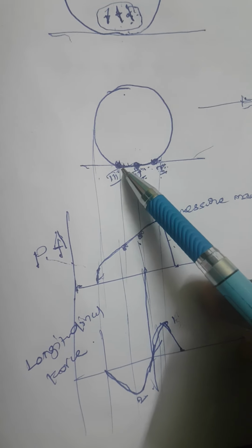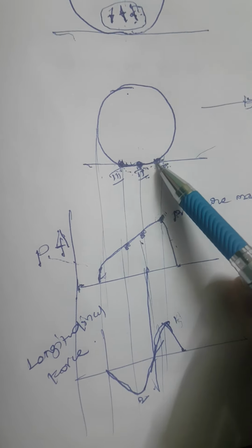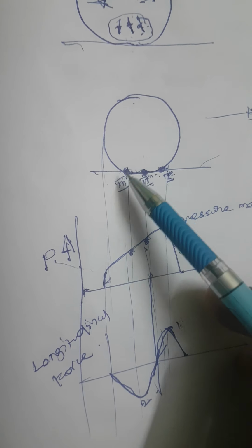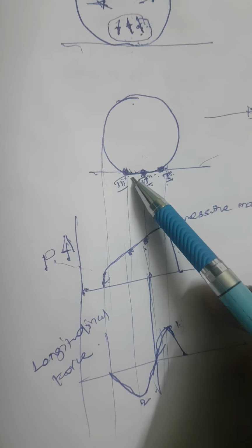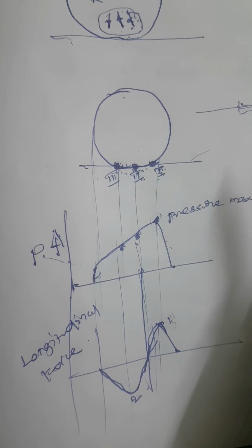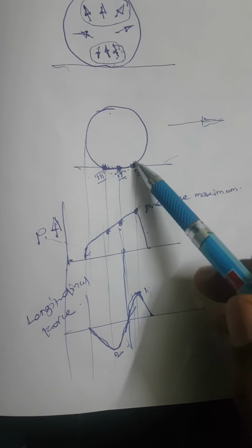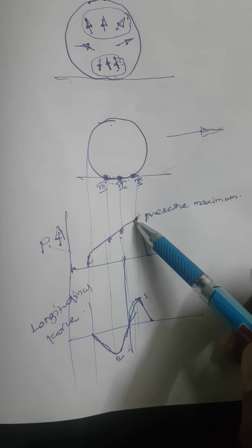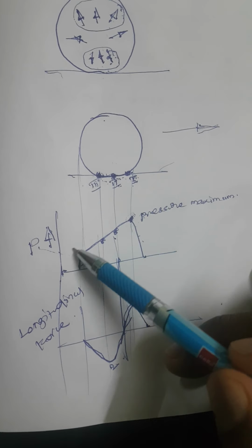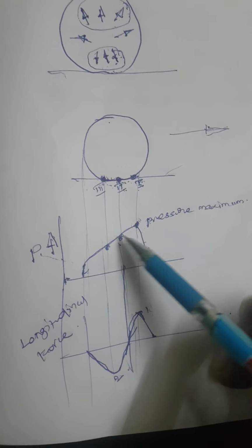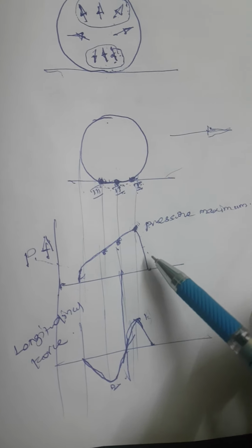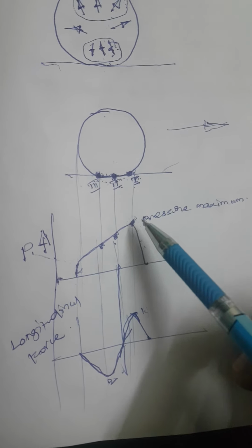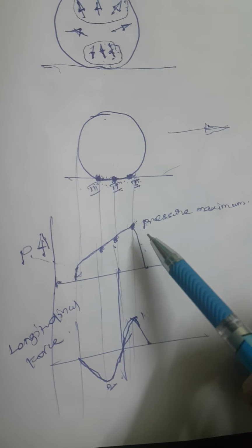Here it is going to release from the pressure. So at the loading point, we get maximum pressure. The pressure distribution is not symmetrical here, it is unsymmetrical. This unsymmetrical distribution takes place because of the hysteresis losses of the viscoelastic material nature. Thank you.